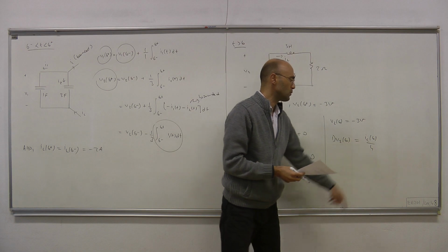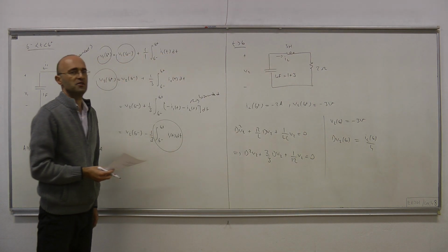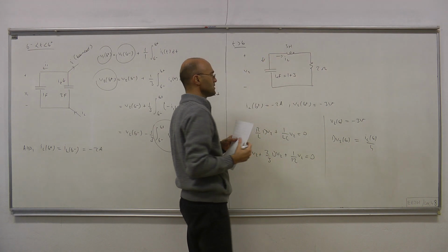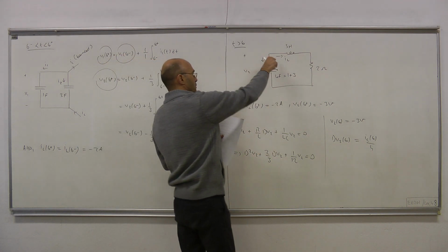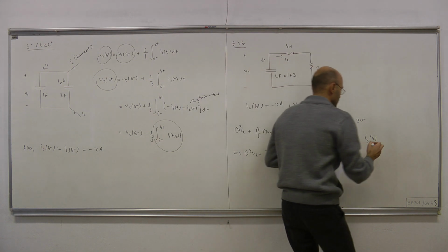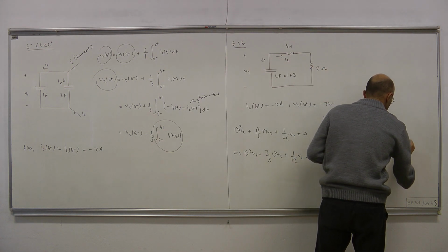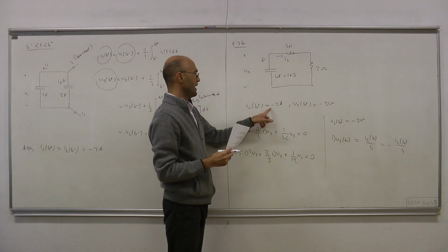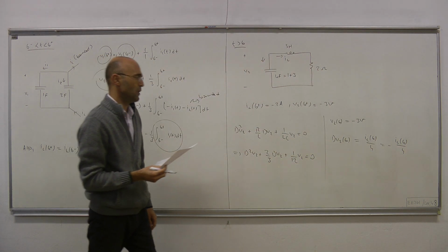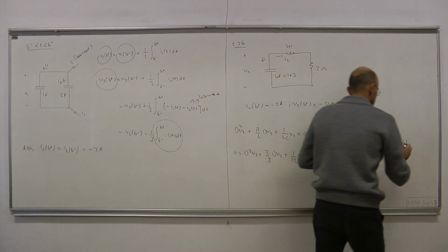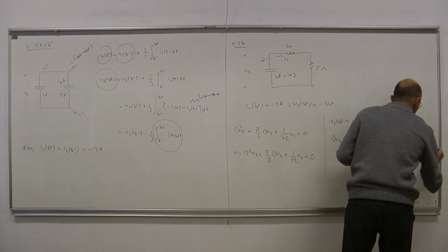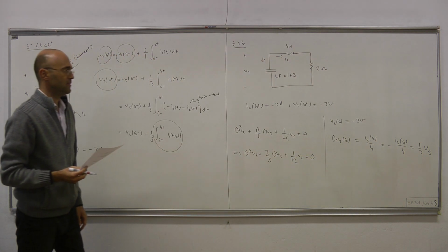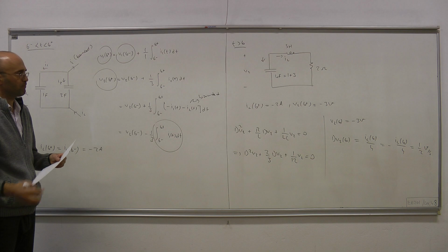Okay, dV2 equals dVC equals IC over C, and this is the current IC, which is minus IL. Therefore, that equals minus IL at 6 over 4, and IL at 6 is minus 2 amps. Therefore, that yields 1/2 volts per second for V2 dot at t equals 6.